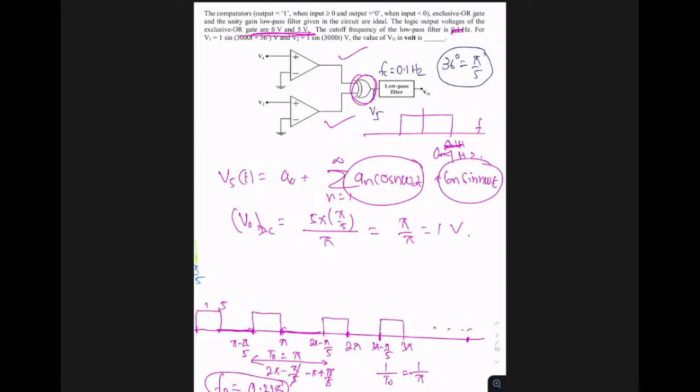Okay, but anyway, one thing I can tell you. If I ask you to find the RMS value, you should be very careful. But if I ask you to find the average value, even if I give the frequency as 0.4 hertz or 0.8 hertz, whatever it might be, you'll be getting different sinusoids. And if you find the average value of the sinusoids, definitely you'll get 0. So always you'll get the DC. If I ask you the average value, it will always be the DC, right? But for the RMS value you should be careful.